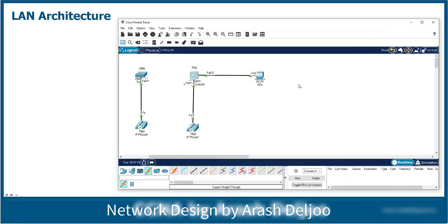Because of that, now we know that the PSE device understands the other side's requirement. If the requirement of the other side is receiving power, the PSE should give the power. If the other side doesn't need the power, the PSE should not send power, or extra power, to the other side. Also, after enabling the power to the other side, we are using CDP or LLDP, as I mentioned before, for negotiating the new needs with the other side.